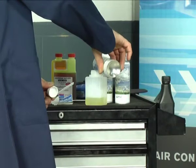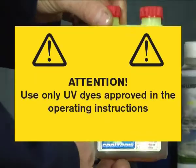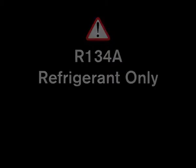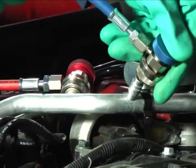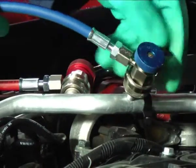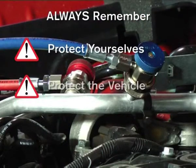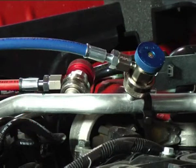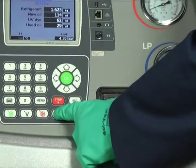Check the refrigerant quantity within the machine and also the oil and UV dye quantities. The refrigerant amount must be between 5 and 7 kilograms. Connect the low and high pressure hoses to the AC system. Please remember, protect yourself, the vehicle and the environment when connecting to the vehicle. If everything has been checked, select the automatic button.